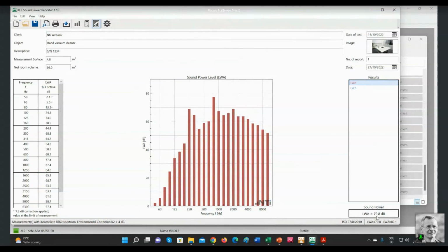to already say that, when you compare this value with the specification given by the manufacturer, the specification is 80 dB. So you can see we are very close to the actual result. Maybe the manufacturer added some headroom to be on the safe side. So it just confirms we have made a correct measurement. Alternatively, we can also take a look at the Z, so the unweighted results in blue color. And again, here, this would be the sound power of the unweighted results.